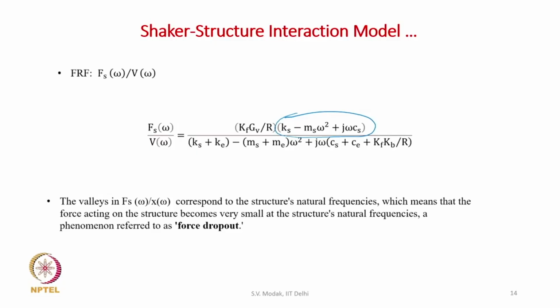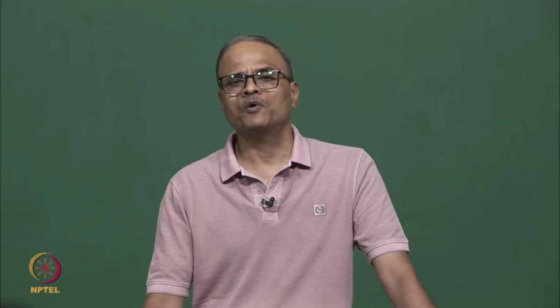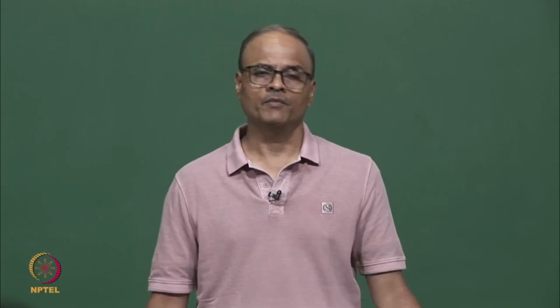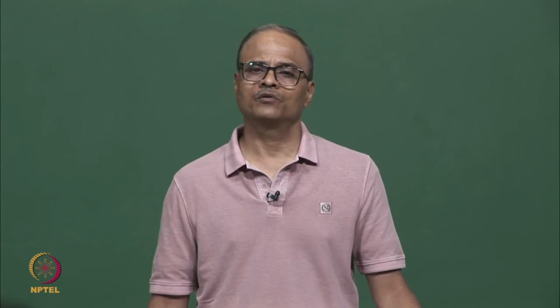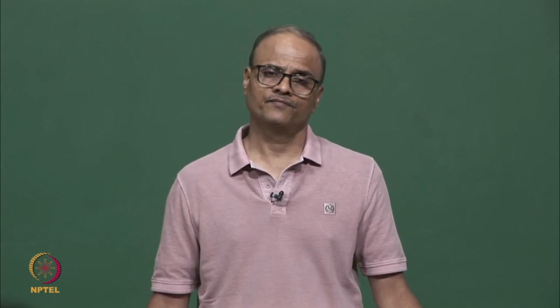So, this is another very important conclusion which emerges from this study. Because of the force dropout, the signal to noise ratio of the force signal becomes poor at those frequencies, and that makes the FRF estimate at those frequencies have larger error.